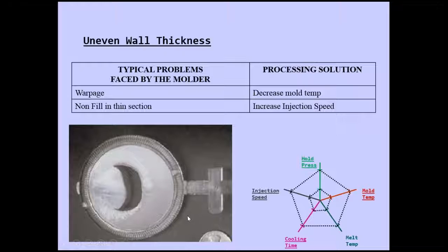Yeah, absolutely. When you're doing a part design, the first thing is don't make it as thick as you can. If you can have even wall thicknesses, you can have flow leaders and flow restrictors, and they'll let the part flow evenly and get rid of this. That will also help you.